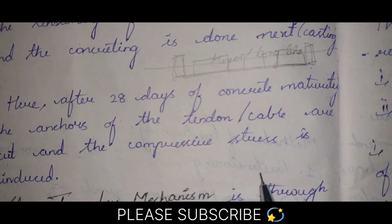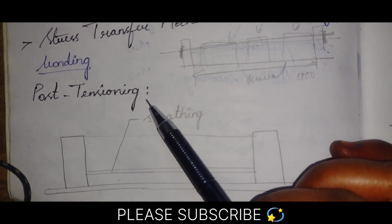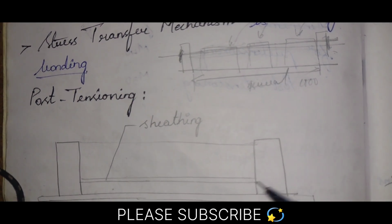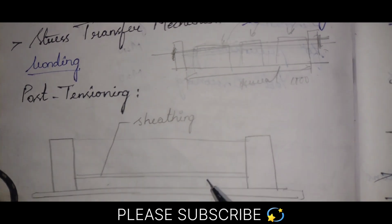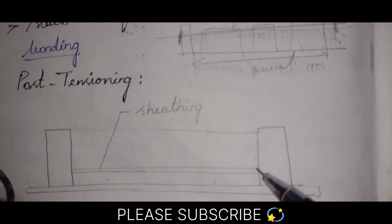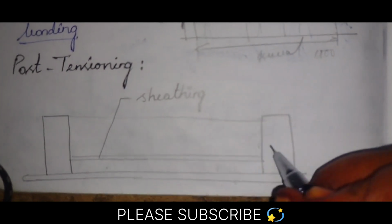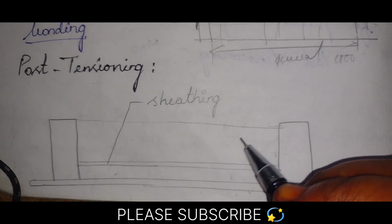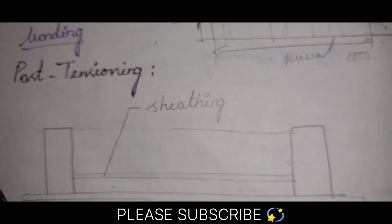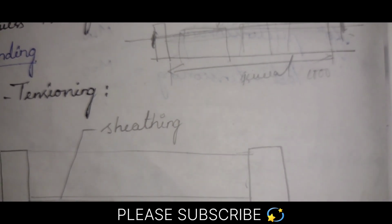Next let us see what is post-tensioning. This is the diagrammatic representation of it. In this method, the concrete section or member is cast first. We provide some ducts for the tension members to pass through. After that they are tensioned with high tensile steel wires.